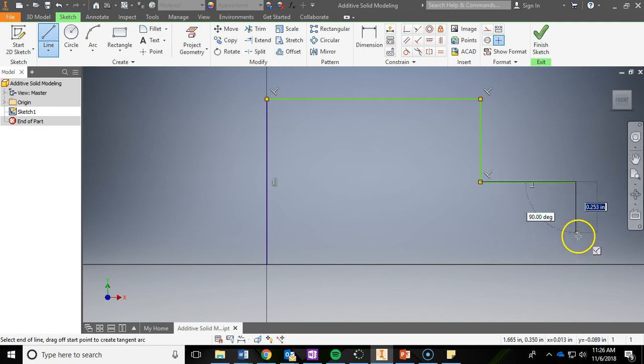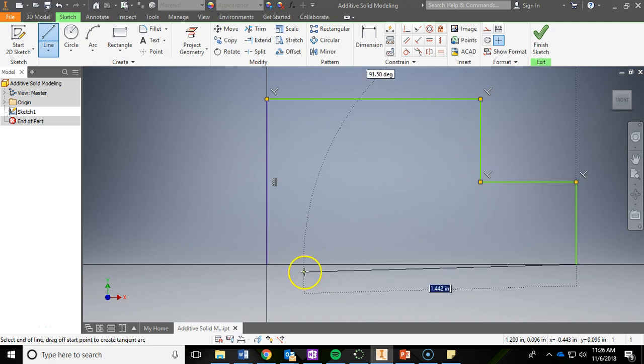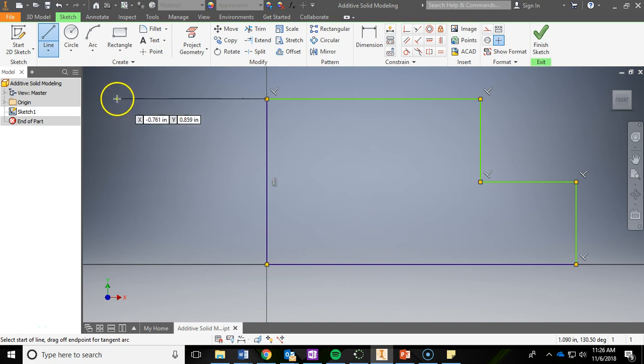Now when I go back down here, I want to make sure it snaps to this x-axis right here. So when you come straight down, you'll see your mouse stop, which is good. I want to snap to that. And then you see that perpendicular symbol, which is good. I want to see that as well. Left click, move my mouse straight over and close it off at 0, 0. Now I'm still in the line tool, so I want to hit escape because I'm done drawing lines.